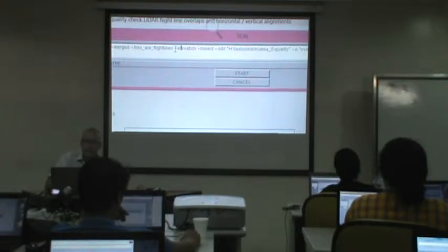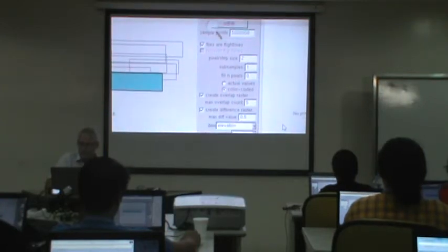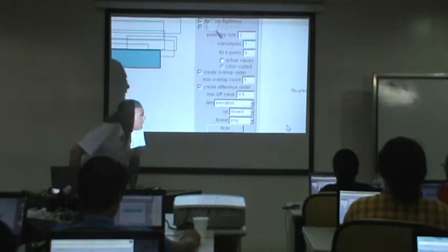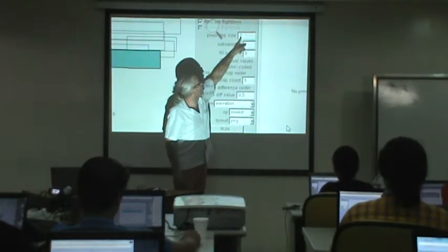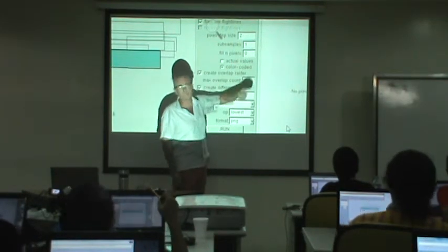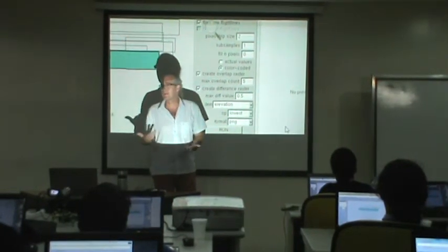We are checking the elevation value, and we are always looking in every 2 by 2 meter cell. We are looking at the lowest elevation value. So that's what this actually means here. And for the overlap, we just look at the overlap. We look at how many points from every flight line fall into every 2 by 2 meter cell, and then we look how many flight lines cover every cell, and then we color it differently.